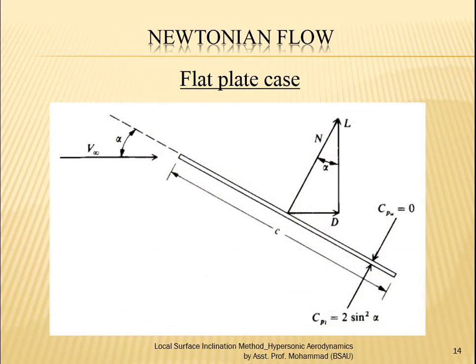Now let us go a little further ahead, to the flat plate case. Here is the flat plate, and this is the angle of attack, and the flow comes here and attacks the surface, then becomes parallel to the surface and loses all the normal momentum. That's what we have observed right now. Now we know that the resultant force because of the fluid is always perpendicular to the surface, locally also, and if it is a flat surface throughout, it becomes a global flat surface also.